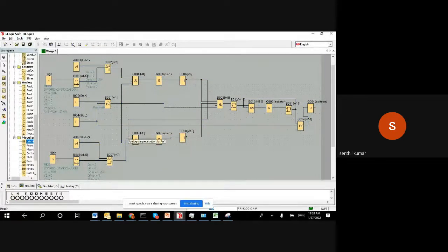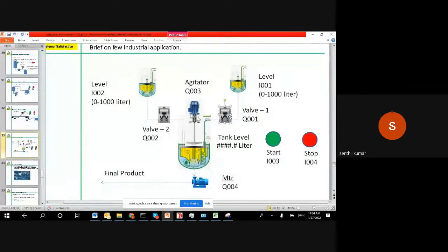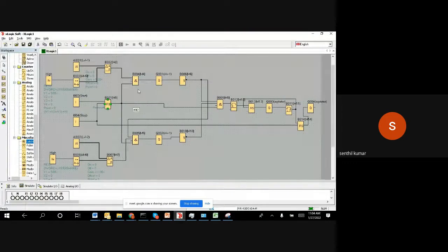I'm going to go offline. I just want to simulate: the first time you start this button, the green button, you are going to set it. Set 1 will come here, and in this leg also 1 will be there, because the tank is full. The tank has 1000 liters. When I push this, I'm opening this valve first. By that time, when you're opening, this tank will have 1000 liters. When it's 1000 liters, we don't want to stop it. So let the valve open. So the valve is open. This is 1 and this is 1. Since both are 1, the valve is open.